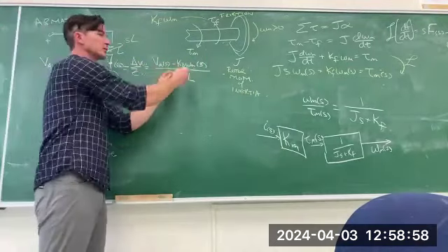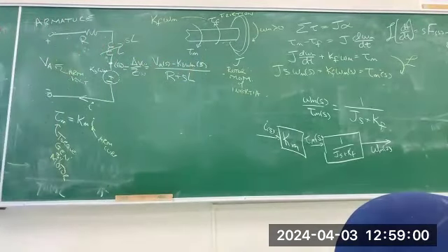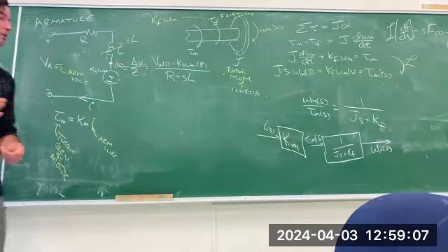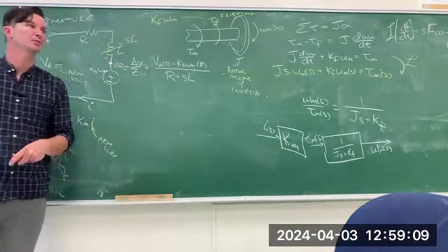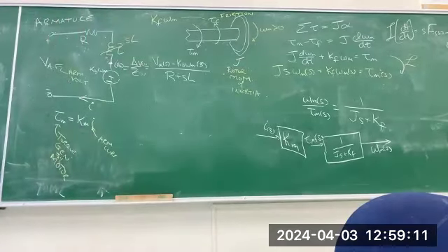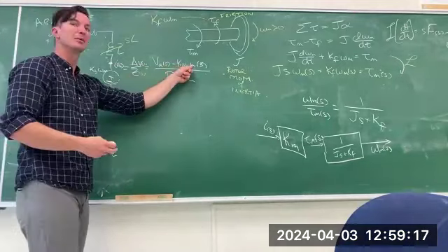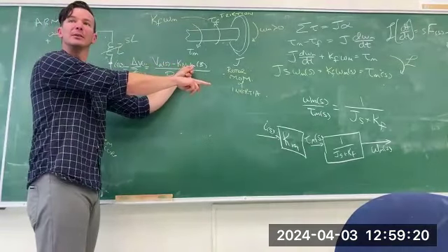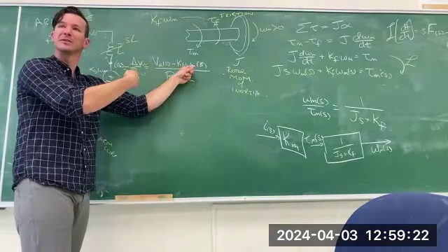So this KB times omega M has got to be in units of volts. And there's a difference here. Like there is a subtraction, that's what I'm trying to say. So how should we model that subtraction in a Laplace block diagram? A summation, but one of those terms is being summed. Hey, it's our output, which gets fed back.